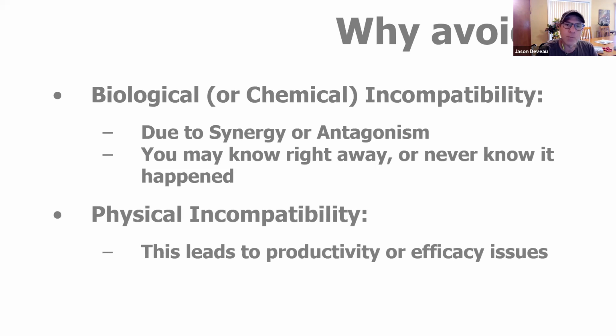If products don't mix correctly, then you don't end up with droplets that have the right amount of active in them. Or as you're driving along spraying, you could be spraying more active at the beginning of the tank and far less at the end. So you don't get homogeneity. It isn't the same. It isn't uniform. You end up with hit or miss. So that's no good.